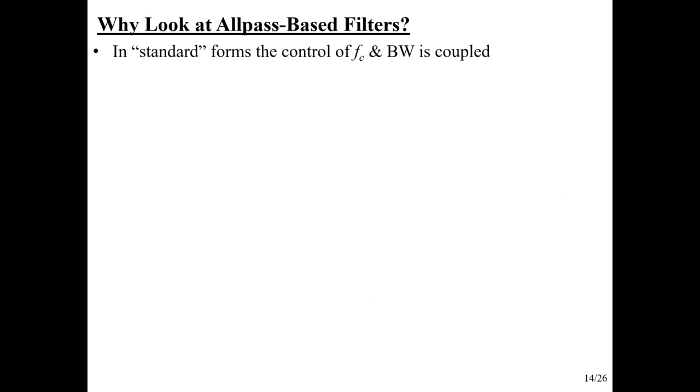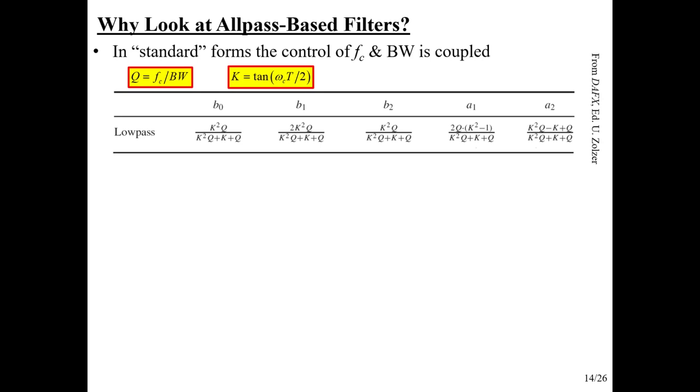So great, we've got all pass filters. What are we going to do with them? We're going to build other filters from them. So why would we do that? Well, it just provides a nice way of implementing them, and sometimes we can gain some advantage because the coupling between cutoff frequency and bandwidth is a little less severe than what we might have otherwise.